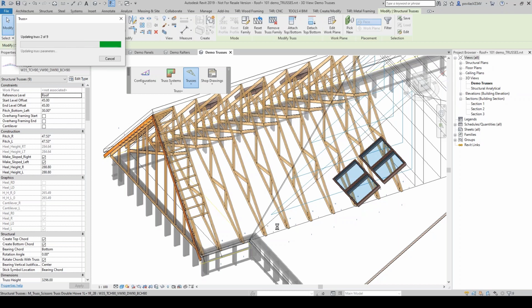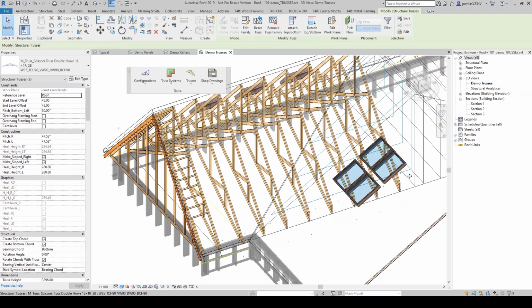Because I have arrayed an existing truss, where in this case it sort of faces the external side of the roof. I have copied that same truss right through where I needed, and it made copies of that truss.